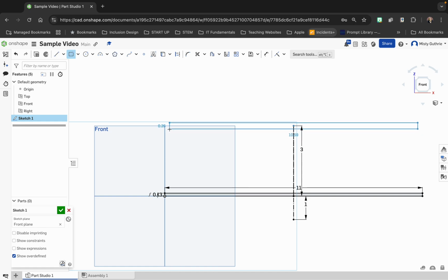In my class, we are allowed to have a 1/8 of an inch tolerance, so that might not be a big deal necessarily, but that may be something that you might be sitting here looking at and saying, well, by the time I add the lateral bracing on the top that we'll do in a bit and anything else, I may want to make this a little bit shorter.